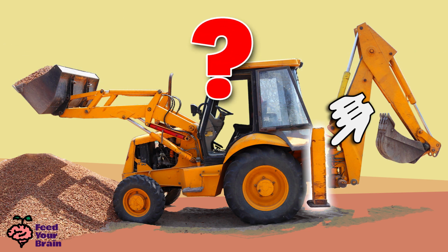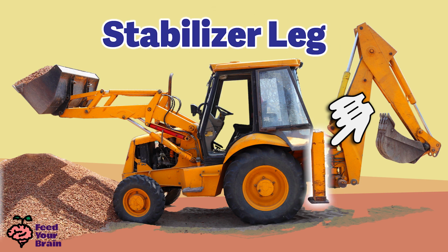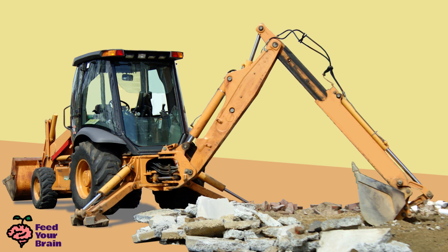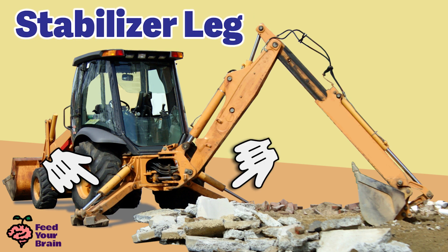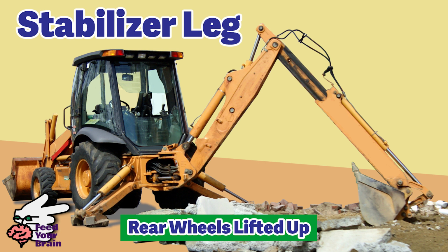What does this part do? This is the stabilizer leg, and there is one on each side for a total of 2 stabilizer legs. These legs are up when the loader is being used, such as in this photo. But let's look at this photo, where the backhoe is being used to dig up a street. Here are the stabilizer legs, and these stabilizer legs keep the body of the tractor stable while the powerful backhoe bucket is digging up the ground. In this mode, with the stabilizer legs down, the rear wheels and rear end of the tractor are lifted up.